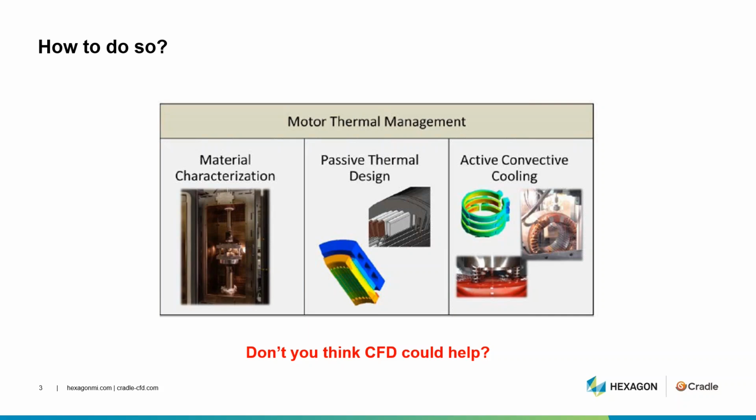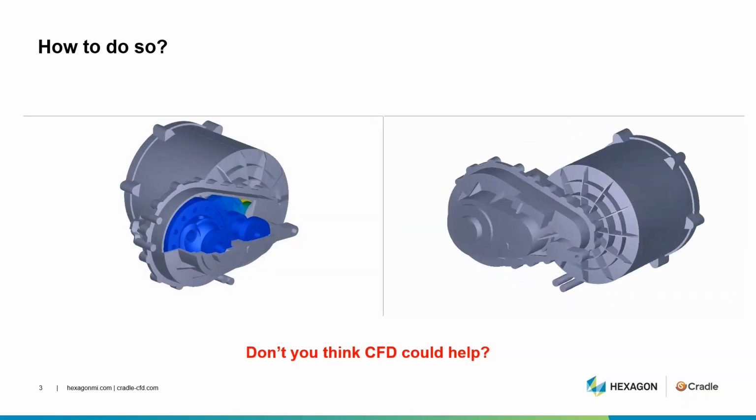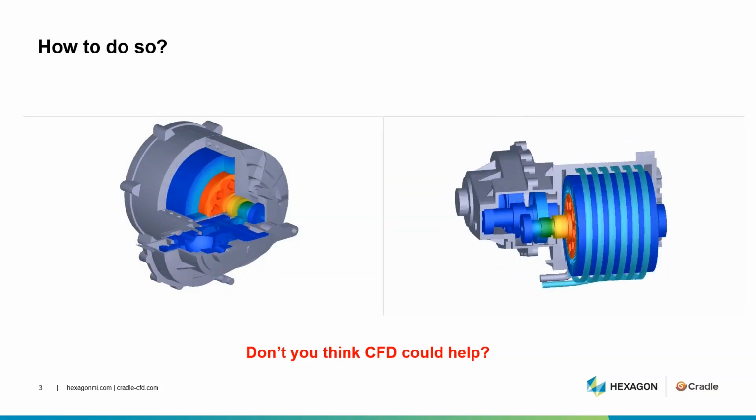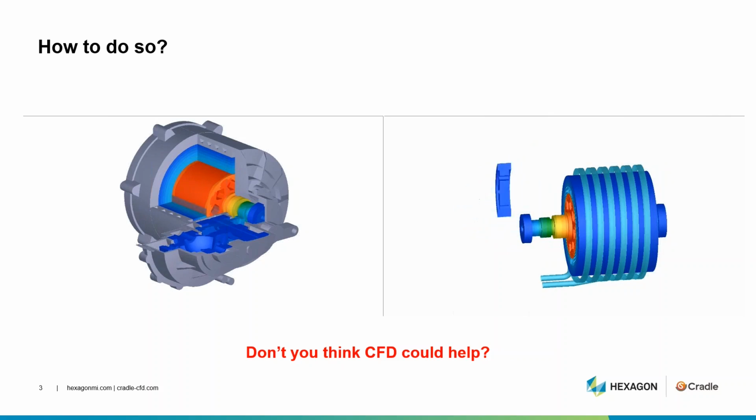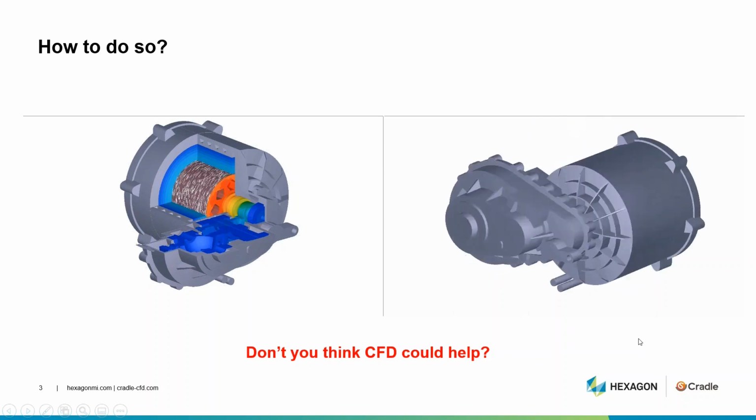Based on these three different solutions, I think that CFD could help here, because in CFD we will input the thermal properties of the different materials. We will also calculate airflow or liquid flow, whether it's natural cooling or forced cooling into channels. So I definitely think that CFD could bring something.